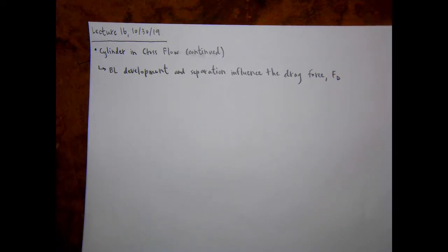Previously, talking about flow over a flat plate, we've only really talked about drag in terms of the friction coefficient that's coming from the skin friction on the plate. Because we now have a wake behind the object, that's going to introduce a new type of drag. So now there are 2 types of drag or friction that contribute to the overall drag force.